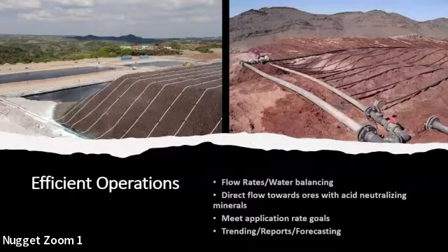All right, now the consolidation permeability results. There's a lot going on here, and the next slide summarizes it in a table, but we'll step through this so you can get an idea of what the results look like and how we evaluate those results. On the y-axis is the estimated heap height or depth within the heap, going from 0 to just over 80 feet. That's our measurement range for consolidation. Along the x-axis is the saturated hydraulic conductivity, which is decreasing from left to right.